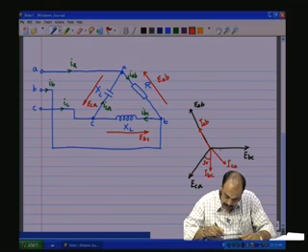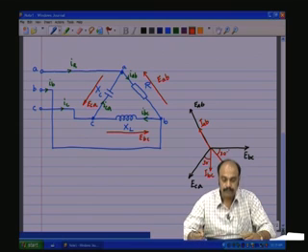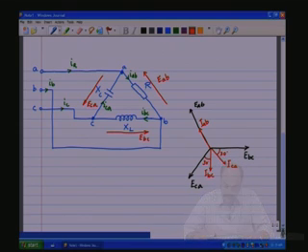If it is 90 degrees to that, it will be 30 degrees from here. So, if I extend the EAB line down, you will have a 30 and a 30 here. Okay. So, this is how the phase currents and the line voltages would look like, the phasor diagram of such an unbalanced system.